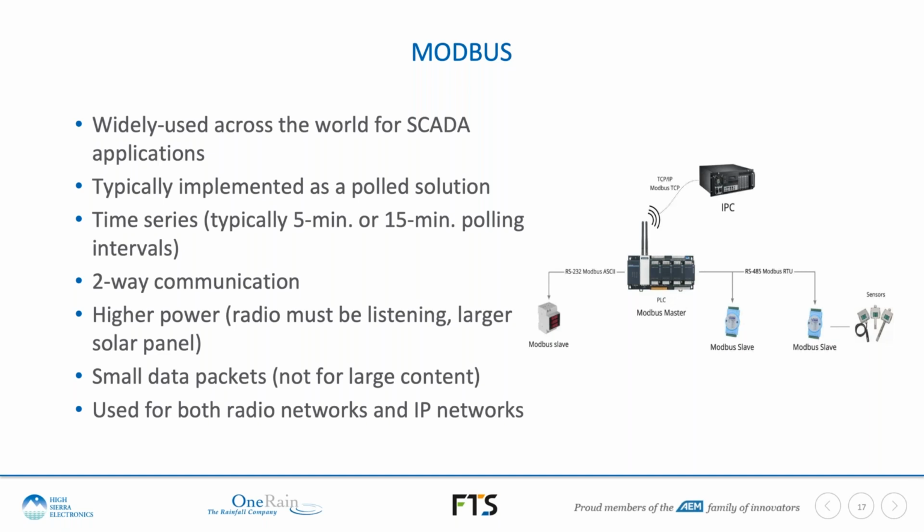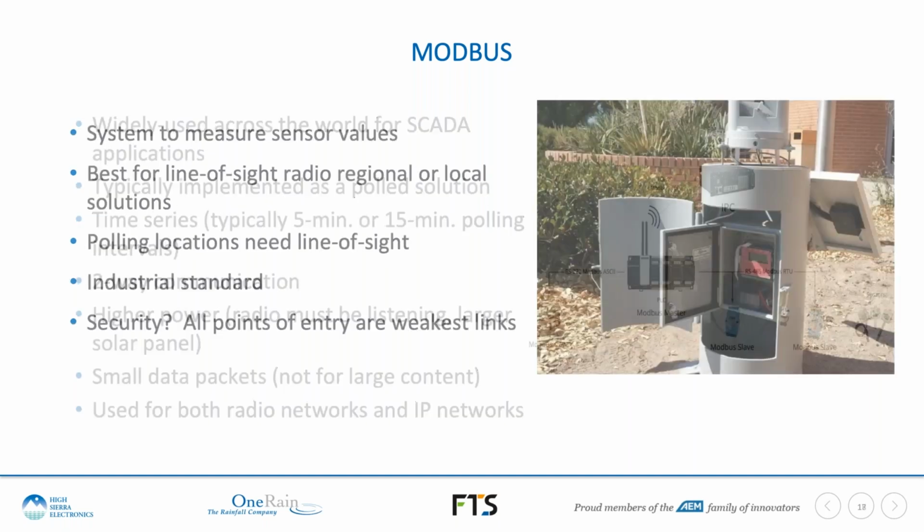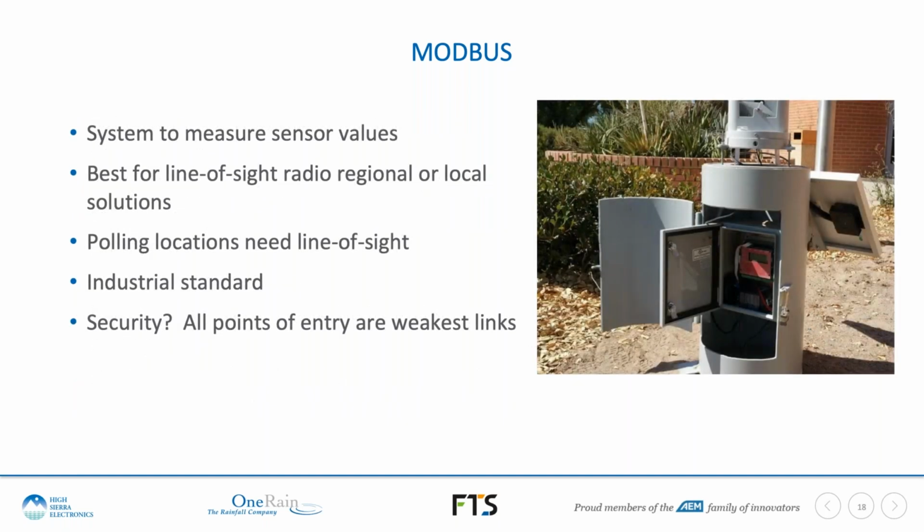So it's fairly complicated, but one agency we're working with has 500 sites that are using MODBUS, and they're polling all the sites to produce 15-minute data, but it requires them to have 3 different radio frequencies. They're actually starting to get full with the number of sites that they can poll because the slots are filling up to support the 15-minute time steps.